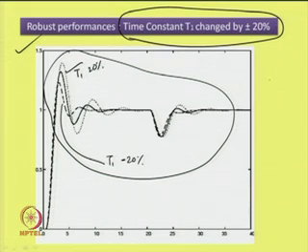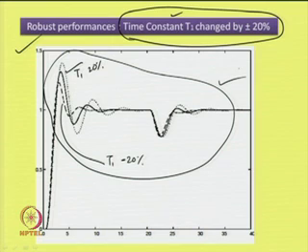Now, not only the time constant, when the steady state gain of the process is also changed, in spite of the changes, the closed loop system is expected to be subjected to better performances, since the PIPD controller has been designed based on suitable phase and gain margins.